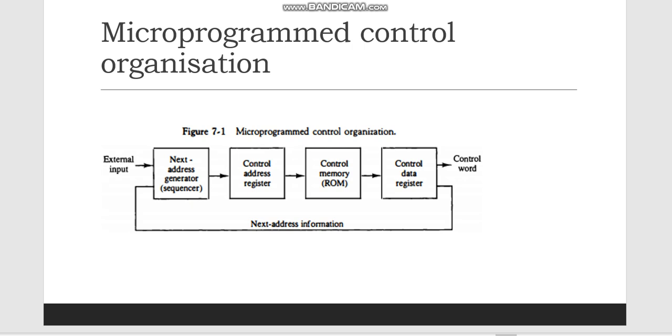When the control signals are generated by hardware using conventional logic design techniques, the control unit is said to be hardwired. Microprogramming is a second alternative for designing the control unit of a digital computer. The principle of microprogramming is an elegant and systematic method for controlling the micro-operation sequences in a digital computer. For example, CPUs with a microprogrammed control unit are Intel 8080, Motorola 68000, and any CISC (complex instruction set computer) CPUs.